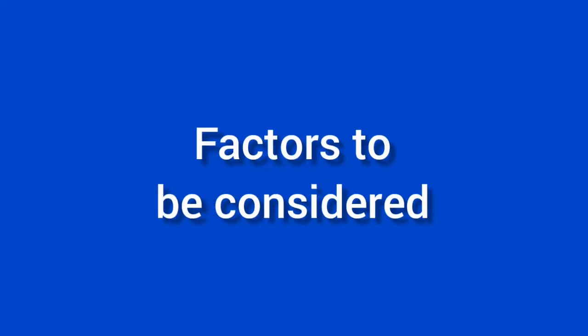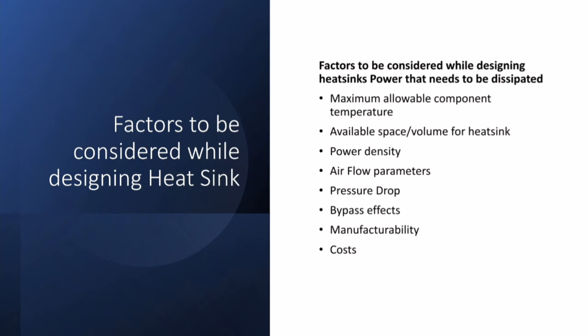Factors to be considered. In terms of designing, factors need to be considered. So factors to be considered while designing a heat sink are powers that need to be dissipated, maximum allowable component temperature, available space or volume for heat sinks, power density, airflow parameters, pressure drop, bypass effects, manufacturability, and cost.